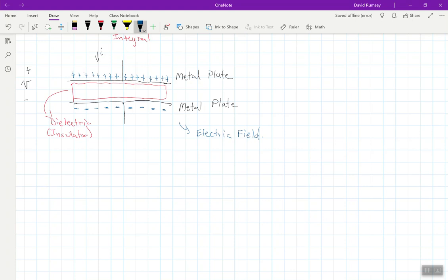Now, as I said, it'd be a terrible capacitor, but it technically would be a capacitor because you've got a metal plate, which is the graphite, on the top side, and a metal plate on the bottom side, which again is the graphite, and then your dielectric, your insulator, is the paper that's in between those two layers. And you might say, well, wait, graphite's not metal, it's carbon, but it's conductive. That's the idea behind it.